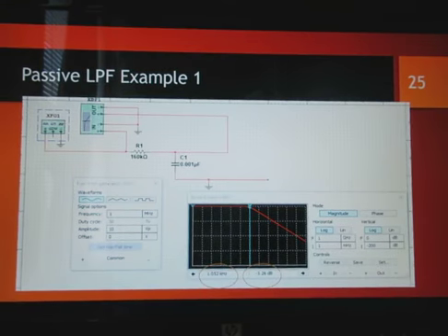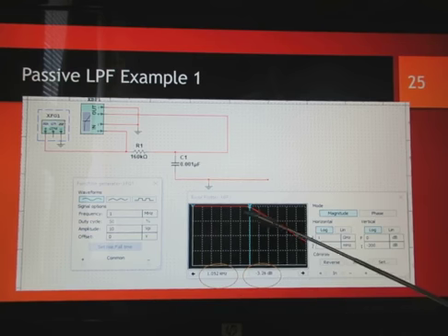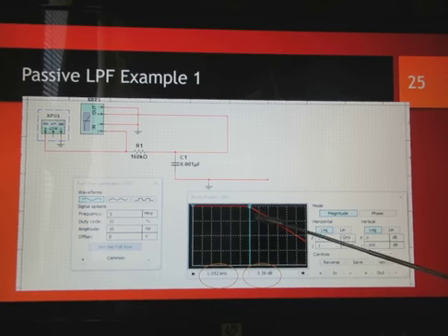So I built this circuit in Multisim, and I set up a function generator for a sine wave at 1 megahertz, way beyond that cutoff frequency. I want to see if it's going to cut it off. And I have 10 volts peak, and I'm using a Bode plot device that's in Multisim. And I noticed the results identified at the circles, I used all default values here. I have about 3 dB is my cutoff range right here, and I have around 1 kilohertz, so it works. And then from there it continues to drop off till it eventually goes to 0.